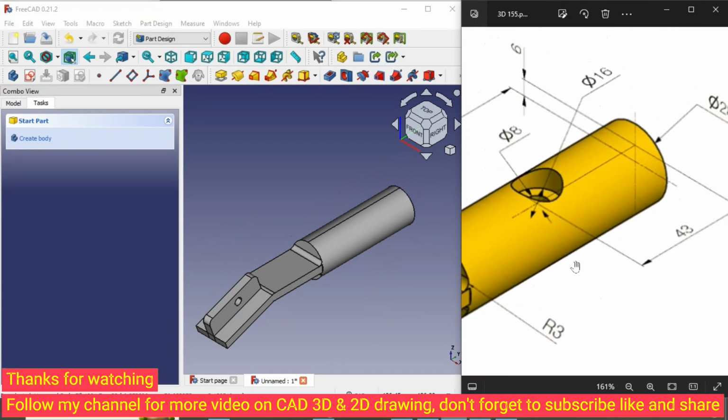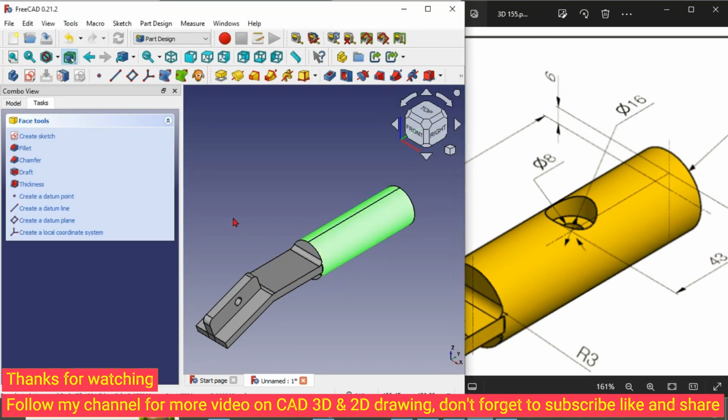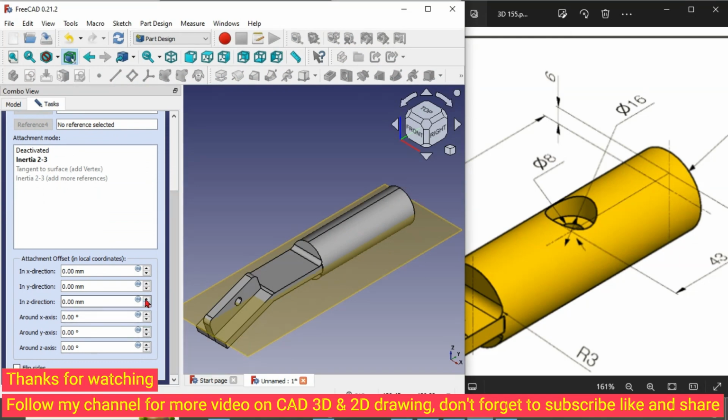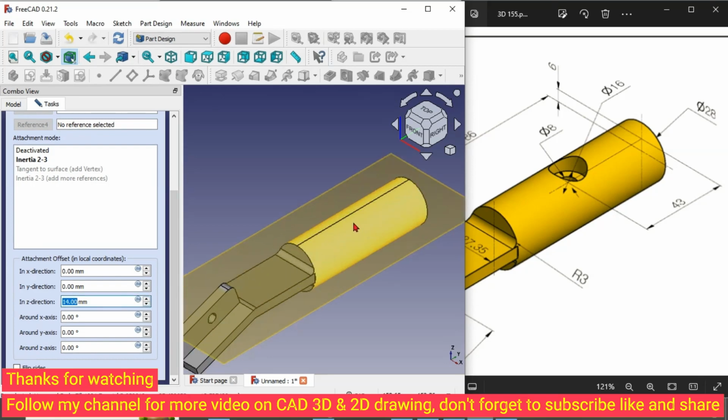Next, we have a pocket and hole here. So you need to draw at the side. Click this. We need to change the datum one more time. For this datum, we just move in the Z direction to be on the surface of the cylinder. This cylinder is diameter 28, so divided by 2 will be 14. So we move in the Z direction from the center to the surface, 14mm, so it will stay on the surface.